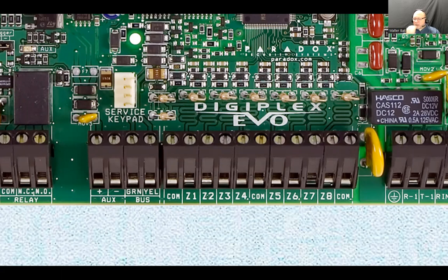But when it comes to terminating alarm systems, the color code is a tiny bit different. For the most part, we use black and red for the power, and yellow and green for any kind of signal coming out of the device. So if it's a door contact, it just has a contact closure or opening. You would only connect the yellow and green. You would not even connect the black and red to the door contact because it's just a magnetic switch. You bring the magnet to the switch and it closes, and you take the magnet away and the switch opens. So there is no power required for that.